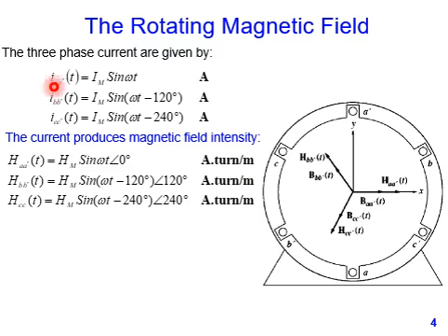The three phase currents are given by the equations in which Im is the magnitude of the current and sin omega t is the sinusoidal part of the current equation. This is for the AA bar winding. Then we have BB bar and CC bar. All these three are 120 degrees apart from each other.